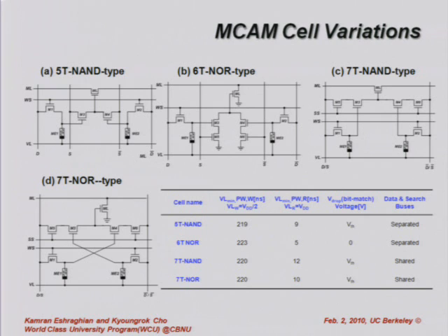They look very similar, but they have some differences. Using 3 voltage supplies, the time for programming our memristors is 220 nanoseconds. Against that, the read time is 10 nanoseconds. It's very fast. Also, for types A and C, the NAND type has some VT degradation due to the serial connection of NMOS on the match lines. We use type D for our design.